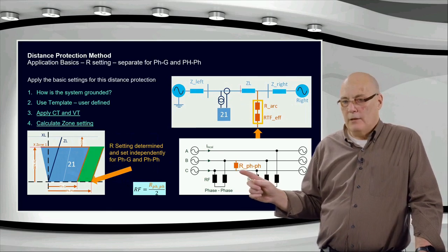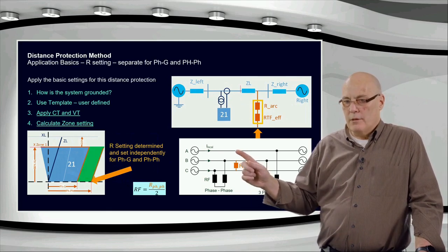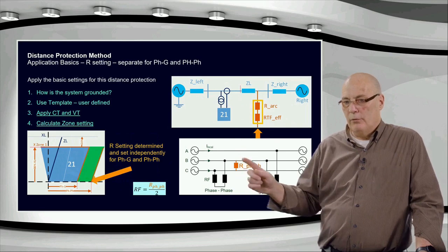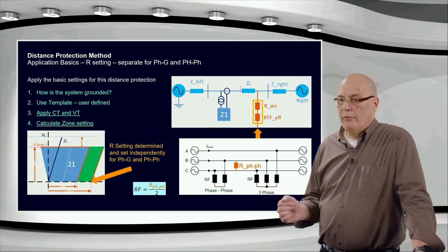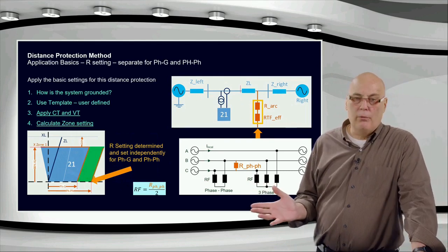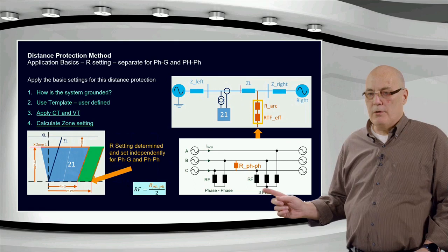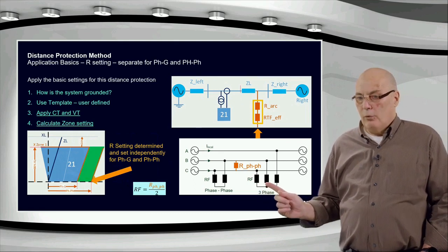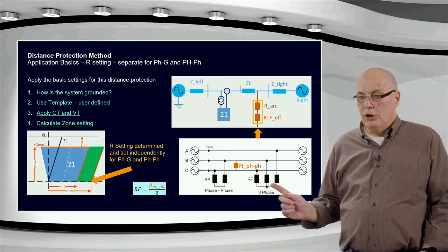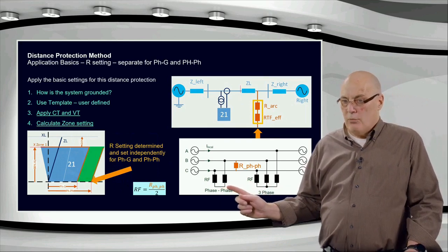You'd have to basically draw 3 resistances here, like a delta connection of the fault resistance. It's not that practical. You could do it for a pure three-phase fault, but what if you had a three-phase to ground fault? It would not be possible. Three-phase to ground fault, you'd have to have a ground connection here. So for the three-phase fault, we assume this definition, and for the phase-to-phase this way, and then they are comparable.